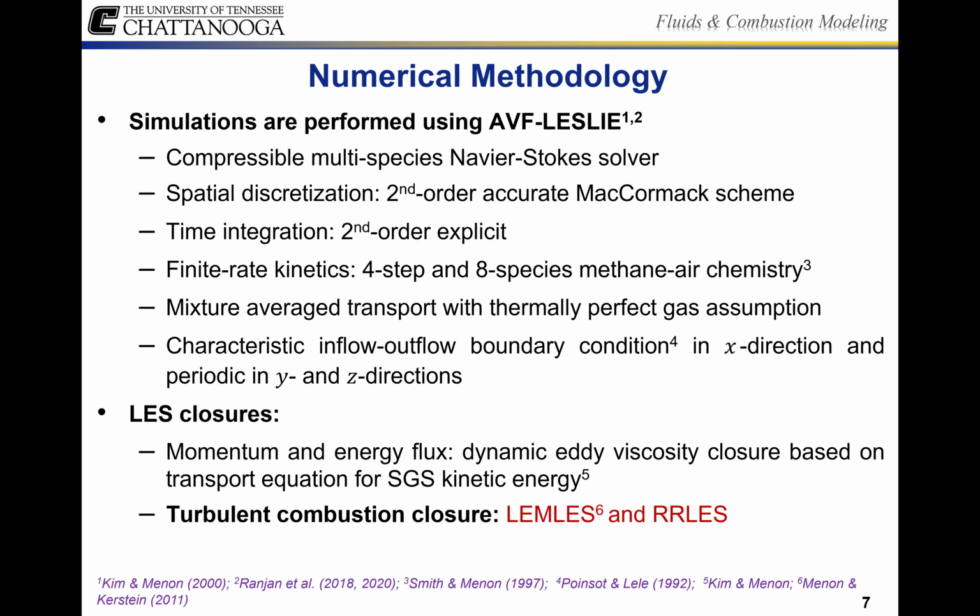All right, so now that we've got some background into the solvers that we're using and what we're doing, let's go over the actual numerical methodology. All the simulations that we did in this study were performed using an in-house, fully compressible, multi-species Navier-Stokes solver called AVF-LESLIE. It was developed by my advisor while he was doing his postdoc at the CCL at Georgia Tech. We are also going to be using a second-order accurate MacCormack scheme, which is very well known, for our spatial discretization. For our time integration, it is also second-order explicit.